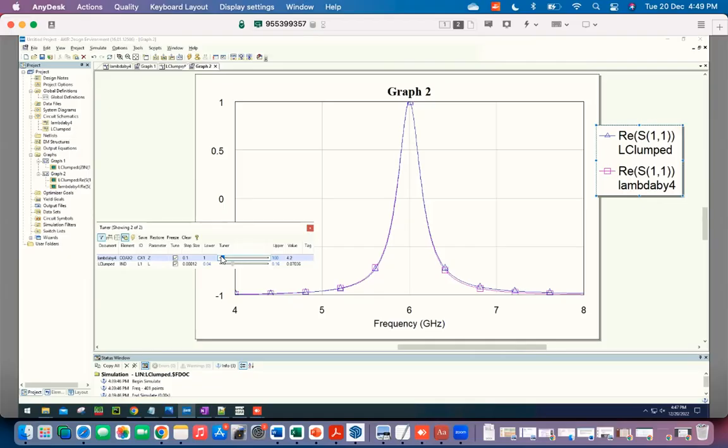There is a pre-factor which comes from the fact that the electric field is not the same everywhere, right? It's zero at the short circuit and it's maximum at the other end. So you have to consider that field distribution. But I guess between lambda by 4 and lambda by 2, there is not that much of a difference in that pre-factor. But this almost only bought you a factor of 2. But that's not nearly enough.